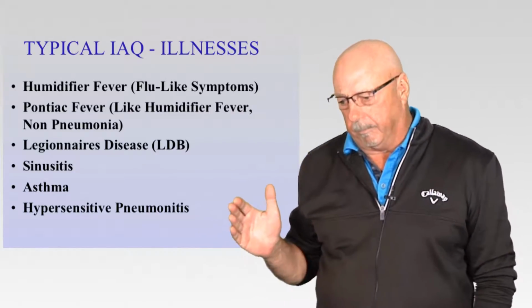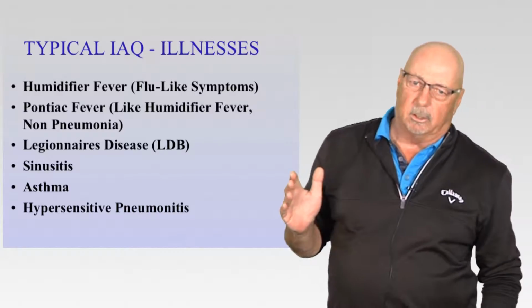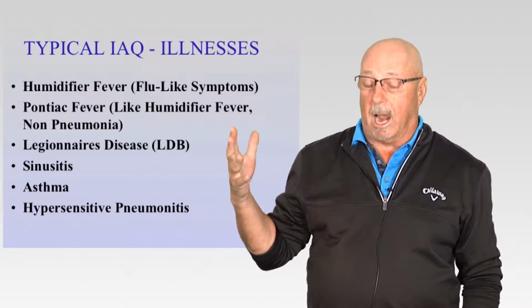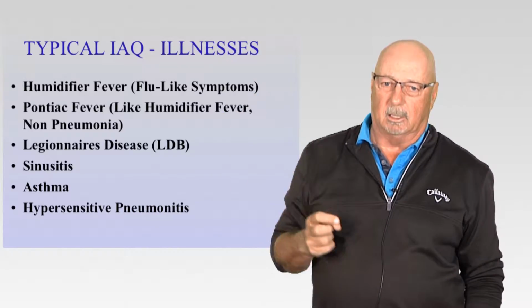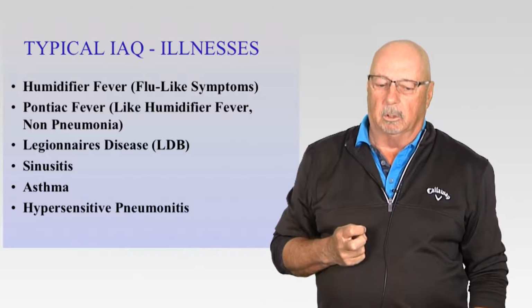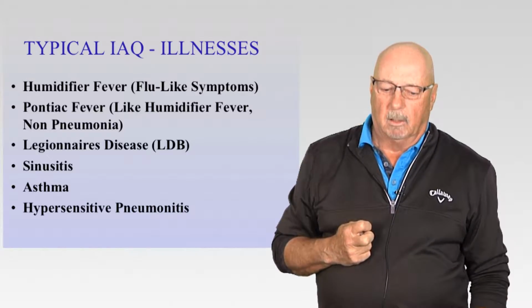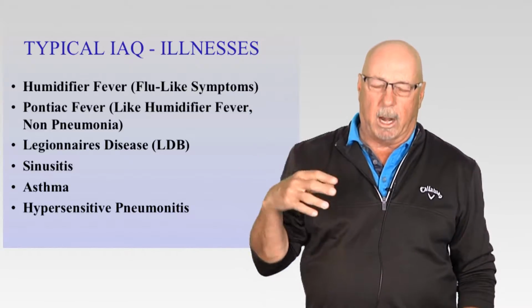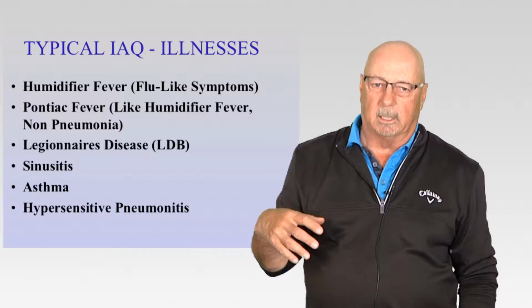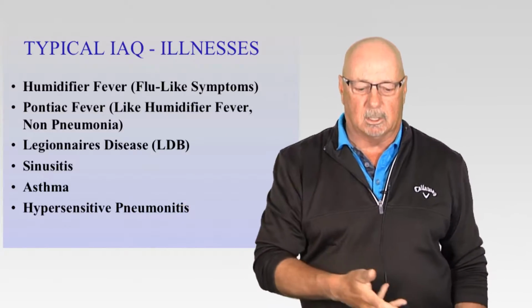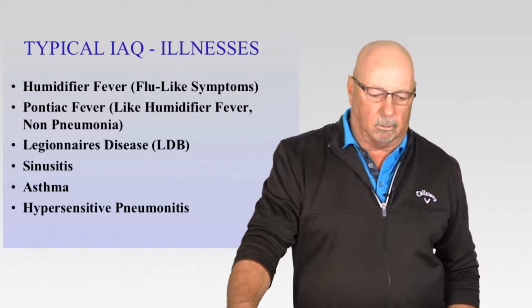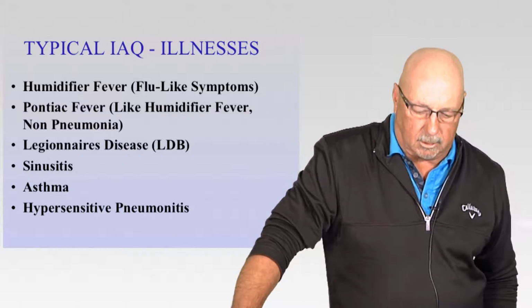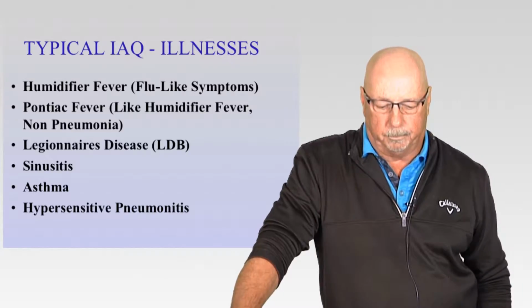However, when that bacteria concentration gets high enough and that water gets aerosolized, like through showers, or in this case at the Legionnaire's disease outbreak, from the ventilation system cooling towers that were on the roof. There would be a spray emanating from those cooling towers, and it was being drawn into the ventilation system and ultimately distributed throughout the building. And that's how the Legionnaires who contracted the illness contracted that organism.